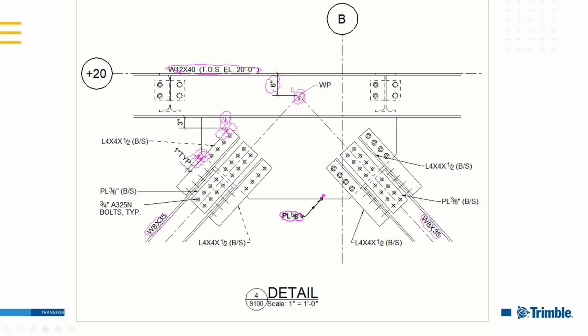And then even my manual dimensions that I added in here, now you can see that this is clouded as 6 inches, and Tekla's even trying to show me with some arrows that this moved up. Likewise here, though my 3 inches did not change, the value of the dimension did not change, the location did change a little bit because of all of our geometrical changes, likewise here with our 1 inch. And so Tekla's trying to show me where those move to and from.